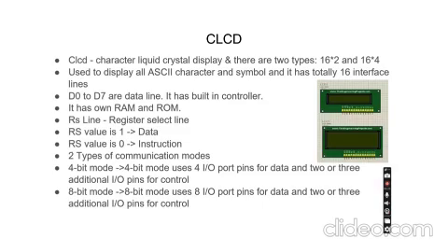It has a total of 16 pins, and the communication modes are divided into two: one is 8-bit and the other is 4-bit. The CLCD also has variants like 16x2, 16x4 and 16x1. 16x2 means it will display 16 characters on a single line, and the remaining are similar.